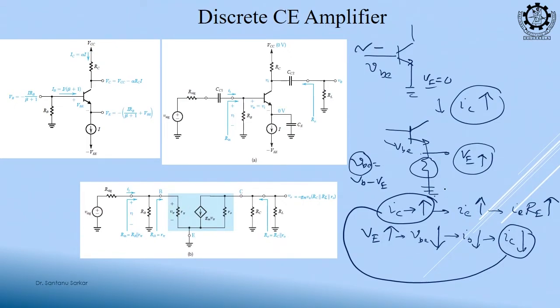You will be saying that okay, where is the feedback? It is not getting back, right. But it is getting back in this way. In the circuit you may say, it is just RE connected to ground, where is the feedback? Feedback is happening this way inside the circuit. Okay. Generally what we see is that something is coming back, right, that is our feedback conception. So, it is happening through the voltages, the voltage it is generating is reducing my input voltage effect.